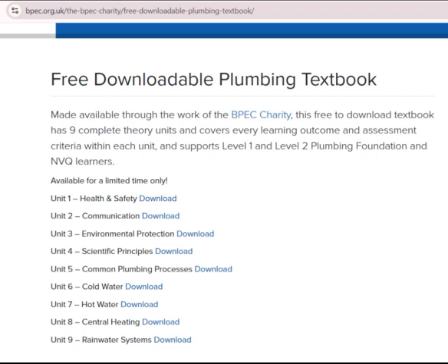BS 659 copper tube was introduced in the 1950s. BS 659 copper tube had a much thicker wall than modern copper tube. The jointing techniques were very similar to today, with both compression and capillary fittings used extensively. Again, the sizes were imperial, and so making a joint requires a special adapter fitting in most cases.